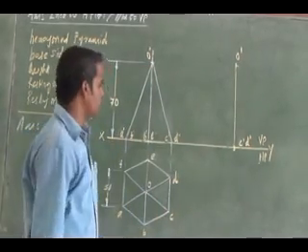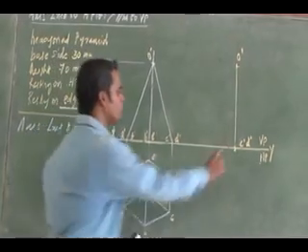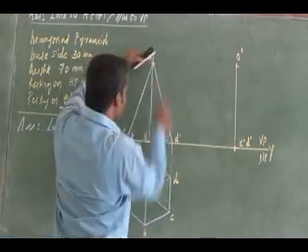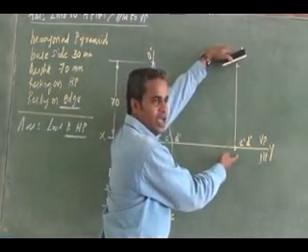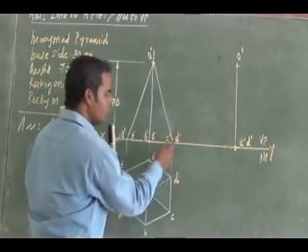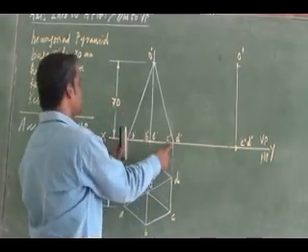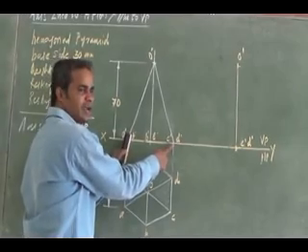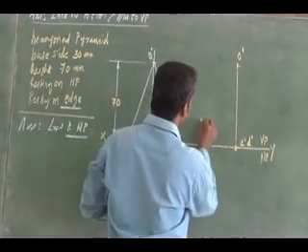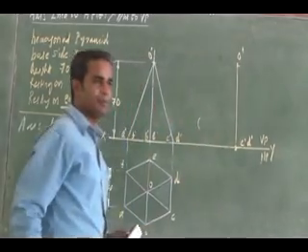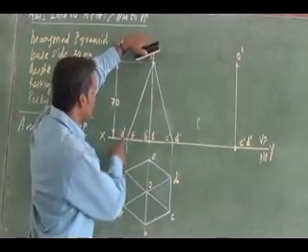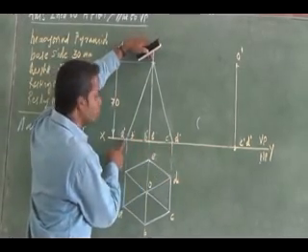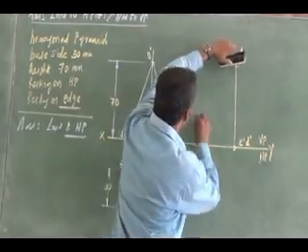You don't need an angle here. I know two destination end locations. In this view, what is the distance from C to A? You measure it from C to A and draw an arc from C. Similarly, what is the distance from O to A? From O, you draw an arc.